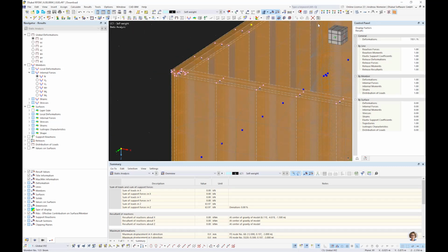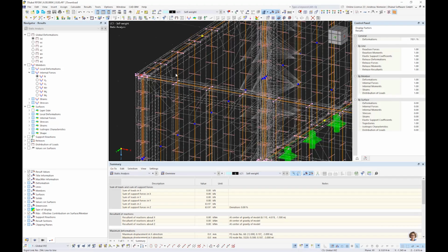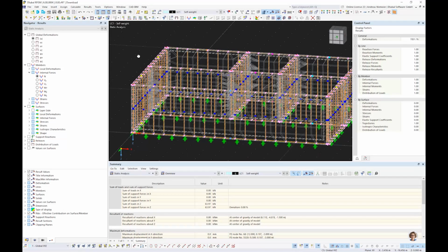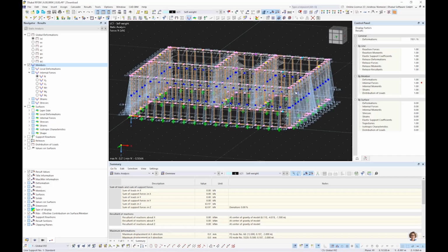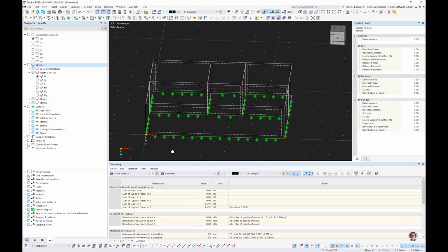We have here, let's say, beams with surfaces, with springs. So there's a really complex model behind, and we defined it only via surface. Yeah, and you can calculate it. And if you watch the forces, these are the normal axial force in the member, how the normal axial force increases. Of course, you have to take more care about loading, but you see you get a calculable model with this substructure idea. Yeah, and you don't have to model it by hand. We only copied surfaces.